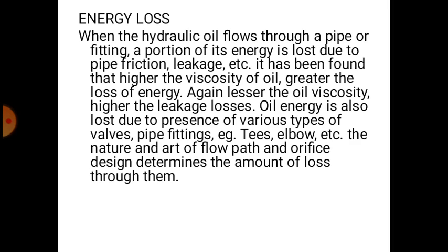Energy loss. When the hydraulic oil flows through a pipe or a fitting, a portion of its energy is lost due to pipe friction, leakage, etc. It has been found that the higher the viscosity of oil, the greater the loss of energy. Again, the lesser the oil viscosity, the higher the leakage losses. Oil energy is also lost due to the presence of various types of valves, pipe fittings, tees, elbows, etc. The nature and shape of the flow path and orifice design determines the amount of loss through them.